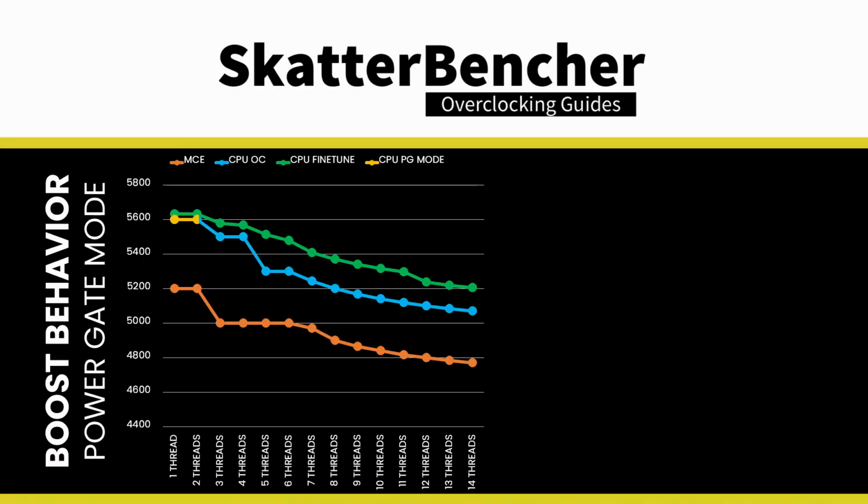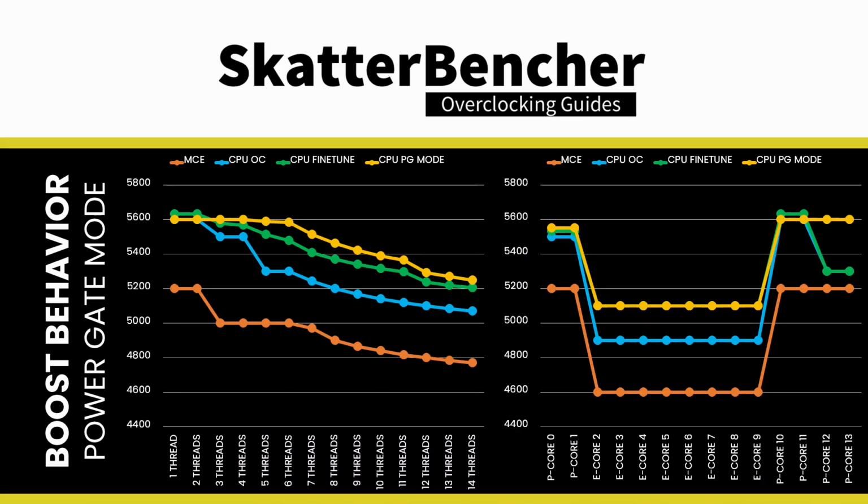the CPU boost frequency with one active P-core is 5600 MHz. The average boost frequency gradually trails off to 5583 MHz when all P cores are active, and to 5250 MHz when all P and E cores are active. In single-threaded applications, 4 P cores can boost to 5.6 GHz and 2 to 5.55 GHz. Every E core can boost to 5.1 GHz.